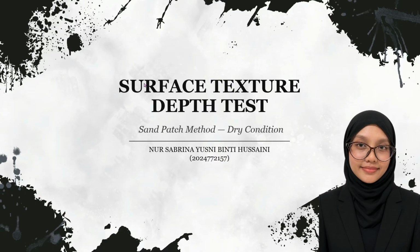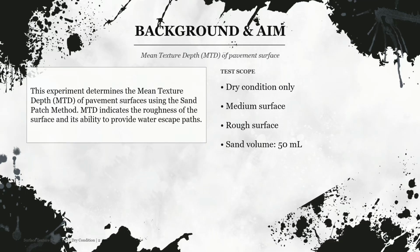My name is Musa bin Yusni, and today I will present about the surface texture depth test using the sand patch method. This experiment was carried out under dry condition only, and the surfaces tested were medium surface and rough surface. This experiment aimed to determine the mean texture depth, also known as MTD, of a pavement surface. MTD is important because it shows the roughness of the pavement surface.